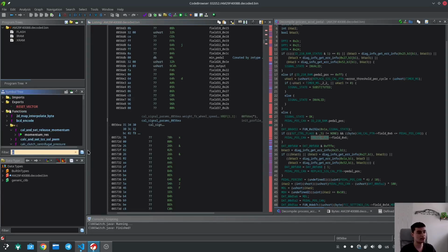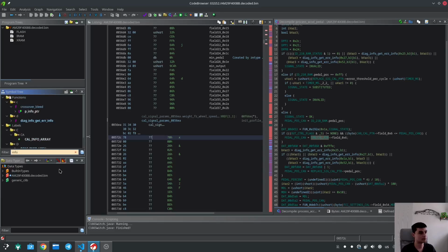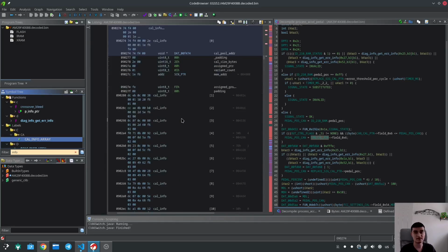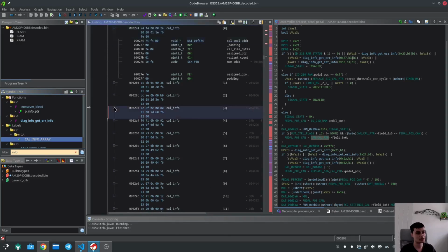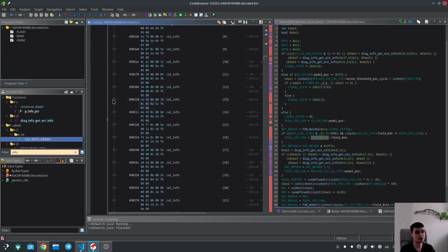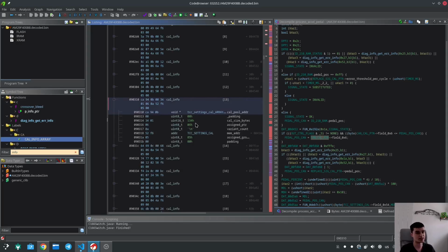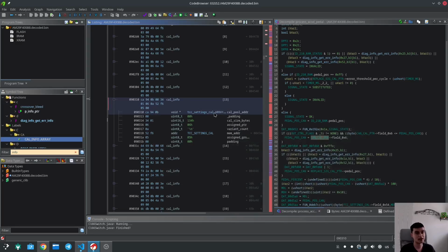And what I found is, if my cursor works... Oh, I can't seem to find it, hang on. Here, cal info array. There is a structure in memory, or in Flash actually, which defines all of the calibrations on EGS. And a calibration is essentially a set of data which the SCN coding string, so this is variant coding, will point to. So in our case, I have here all of these calibrations, and for instance, this one's the torque converter settings. Now here, for instance, I can see this is the pointer to memory, this is the pointer to Flash, where all of the calibrations will be stored.